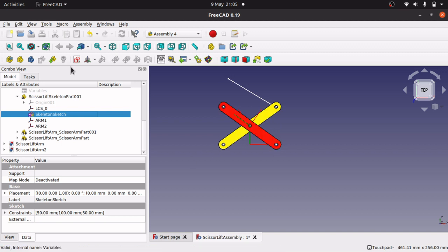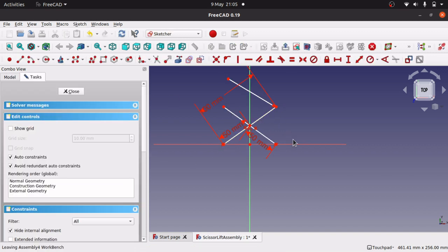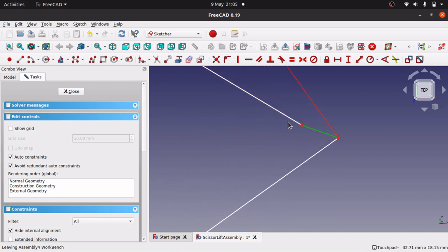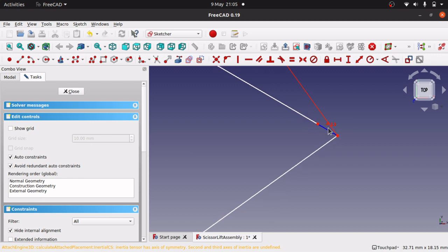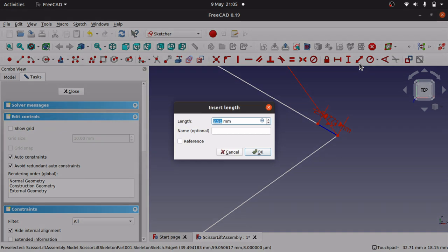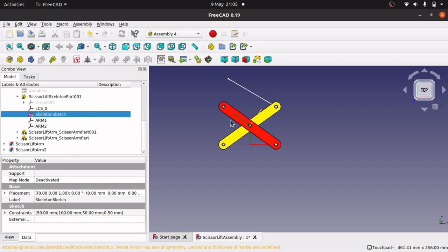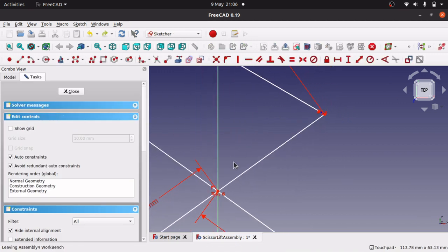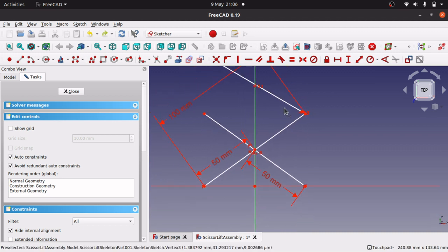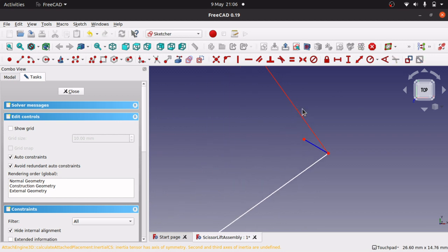and it's back to where it should be. And we could just come in here and just make those parallel to each other and just put some kind of arbitrary length in here, again like 0.5 millimeters, and close that, and we've solved our problem. Now one thing you would notice also if you're looking closely is that you see I've got a point here, and there's a reason for that as well, and that is because of the topological naming issues. I'm just going to get rid of this piece of construction geometry.